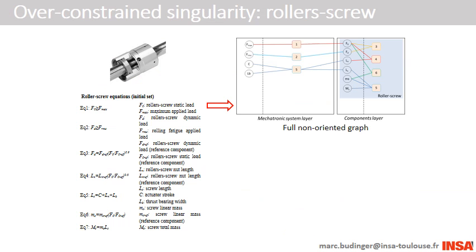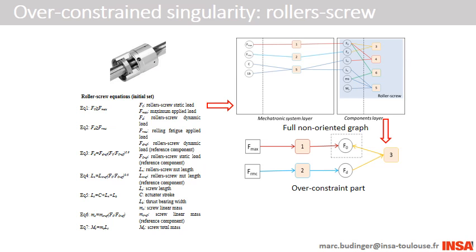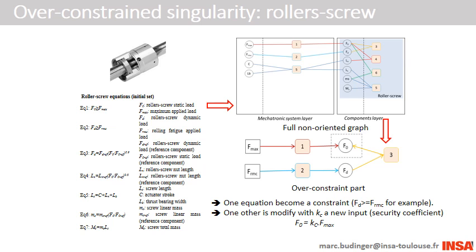A second type of problem can be encountered: over constraint equations. While we select roller screws, the choice can be determined by static and dynamic limits criteria. One quantity can be influenced by two equations, here F0. One solution consists in transferring an equation into the solver constraints. For instance, the dynamic load equation 2.